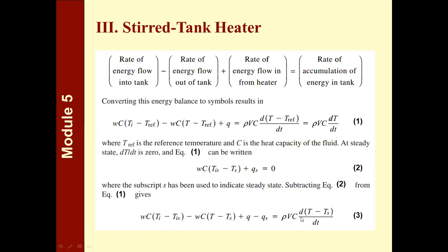You do not relate the temperature to changes of both of these. If you have changes in both the inlet temperature and the amount of heat introduced into the tank, you will not be working with a transfer function. You will really be working with the differential equation itself, because you already have two variables that are both changing, which would affect the behavior of the variable that you're trying to monitor or measure.